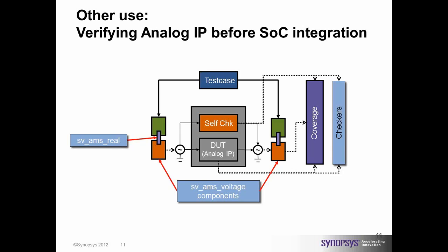A typical example of that which I can take is an ADC. Now I can write constraints to drive the node, or the V in, with a value from 0 to just 1 volt, given that the range for this particular ADC is minus VDD to plus VDD, say minus 1.8 to 1.8 volts.